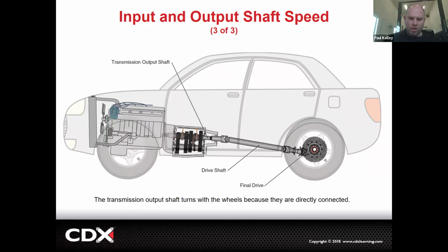Okay, from there, I want to explain why this is so relevant for you, not because of race car stuff. If you had a problem, just like this Jeep right here, this piece of junk, when I push the clutch pedal down, remember I already pre-told you, I think it's got air in the clutch line right now. When I push the pedal down, the clutch is still dragging a little bit. So when I go to shift, the shift is hard. Like going into first, it takes a little extra effort. And when it goes in, you can feel it. It's sort of like still engaged. The clutch is definitely still dragging a bit.